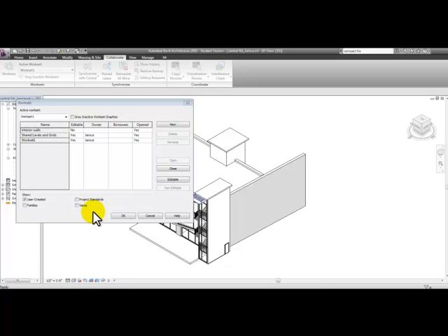Many projects are also separated by shell, interior, and furniture. The Yes means that you are the owner of these elements. Better coordination of the central file information, but constant coordination within the team will assure success. If you put a check mark here, Revit will gray out all of the elements that are not part of your workset and will not affect the plotting quality.